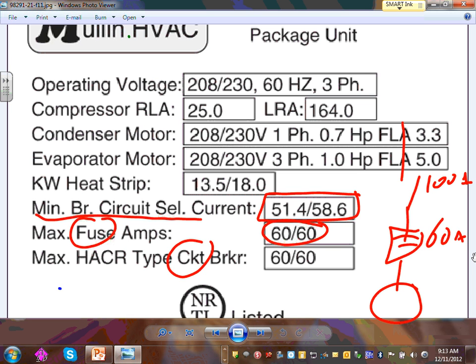And my conductors, look at my conductors. Which voltage are we going to be using? We're going to be using 208 or 240. Are we using 208? At the top, is it 208? Can you guys look at it? We're using 208, so that will give you the higher voltage. Then we can use this amp times 1.25 and we size these conductors right here.